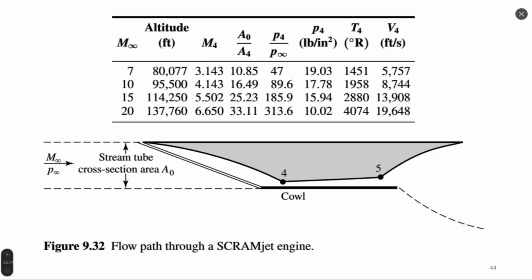Usually recommended values are close to 10 diameters. So the length of a combustion chamber is 10 times bigger than its diameter, more or less. There are also some additional devices that could be installed inside it to simplify the combustion process and reduce these lengths.